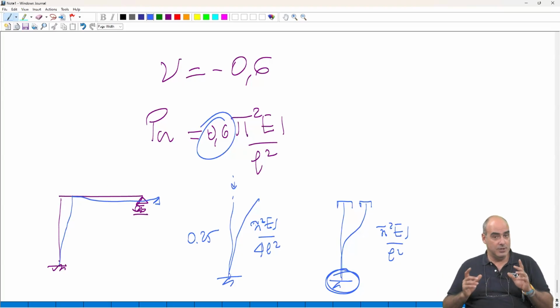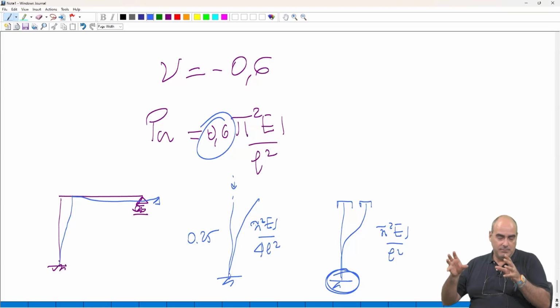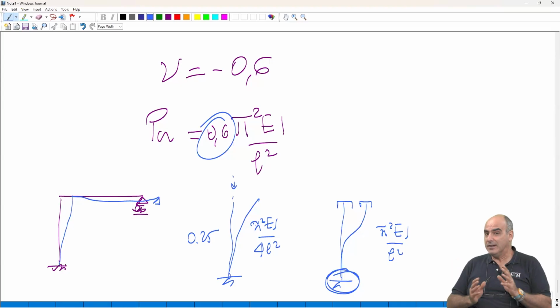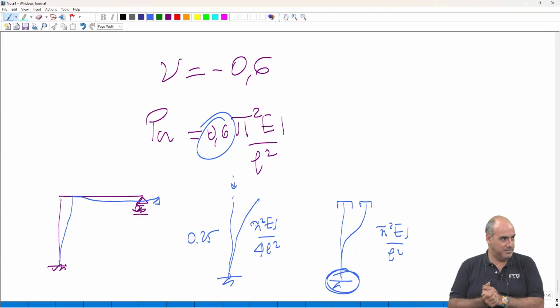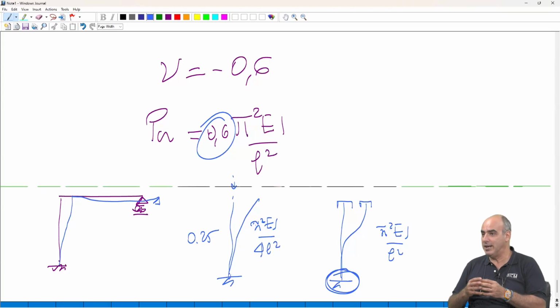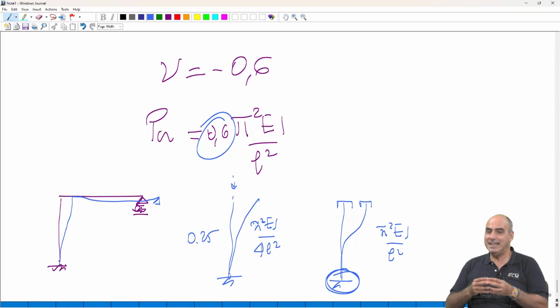And generally, the parts of the element to be connected are concrete elements. And the forces which pass there, in most cases, are strongly multi-axial, but with a predominant component of shear forces. At the support, the shear dominates. Shear is a brittle failure mechanism. The devices which connect the elements are generally steel. Steel is ductile.